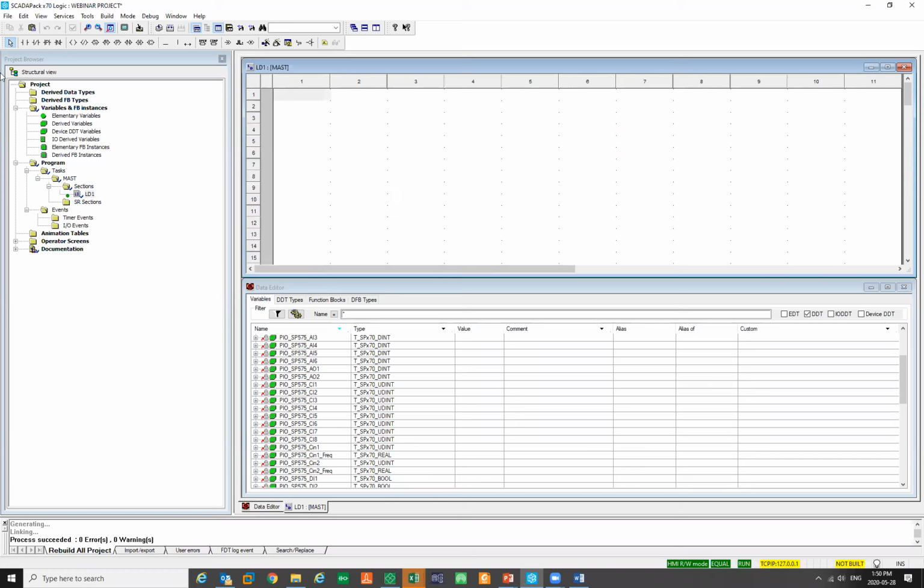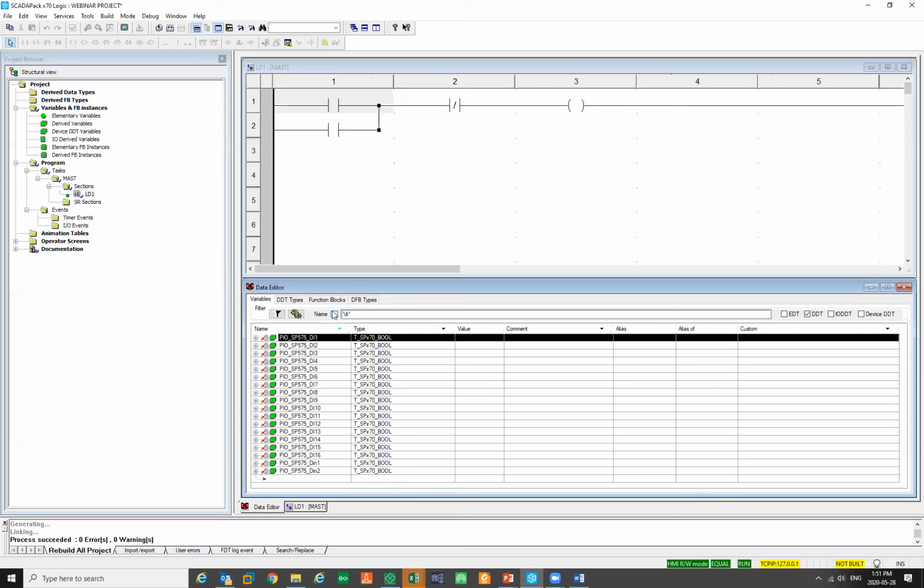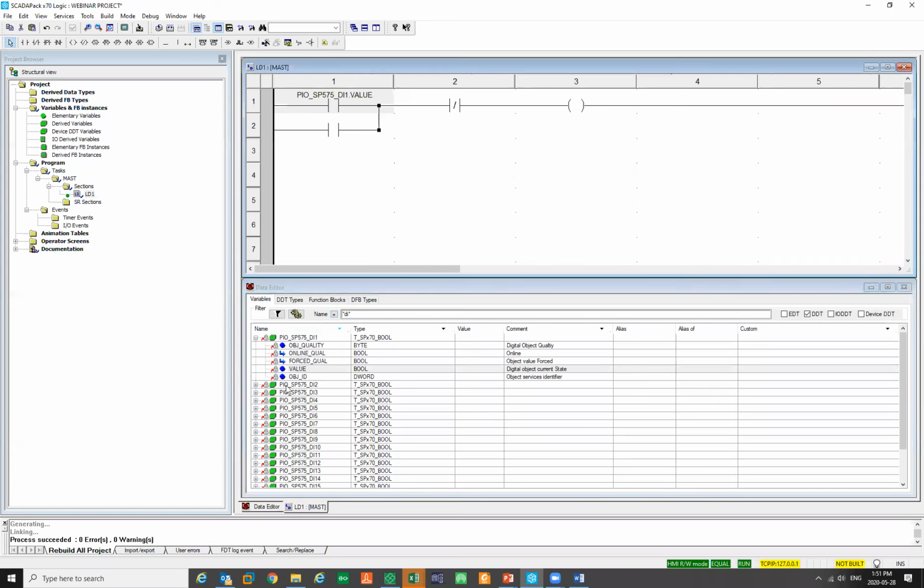In the ladder diagram here, we're just going to put in some context, a little bit of motor starter logic, very simple. Just branch that together, get the volatile latch ready. Now to add some inputs to that code, we can just drag these over.